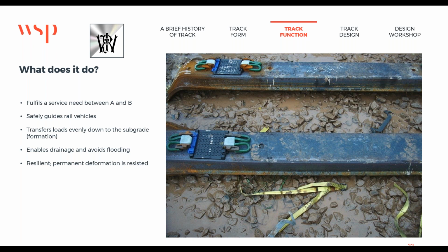The effective control of water is essentially part of the safe and economic management of any railway infrastructure. Water has an important and dominant role in most of the degradation mechanisms that affect track infrastructure, such as the scour of flood defences on bridges, and it affects the track by having a long-term softening of material that form the track support system. The cyclic loading is an issue. So as the wheels load the sleeper, it transfers that to the subgrade. Every axle on every train has that pumping up and down effect.